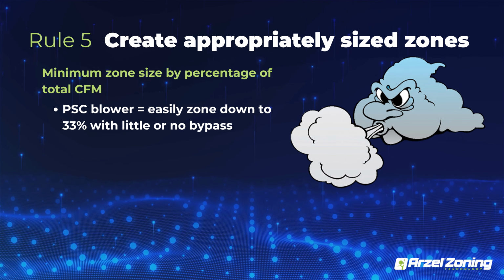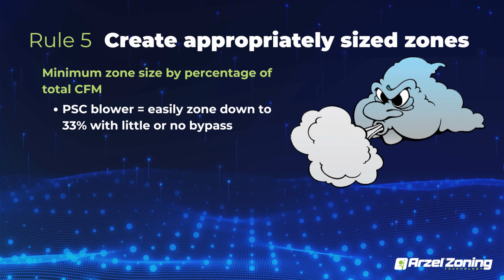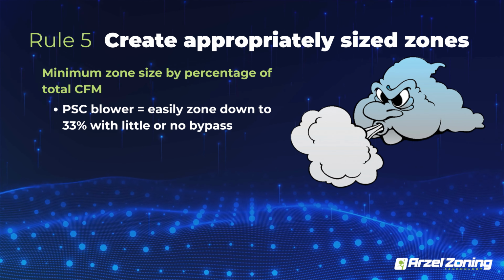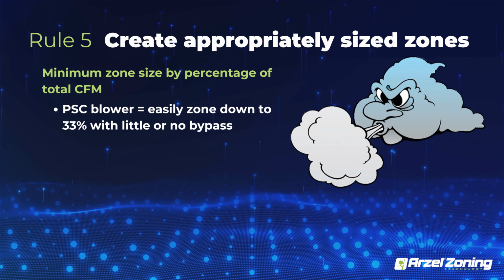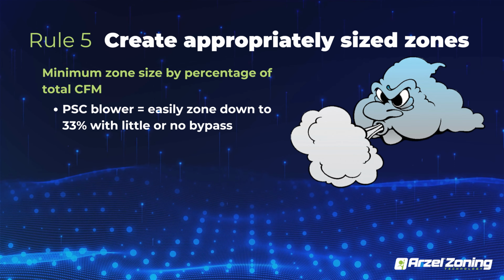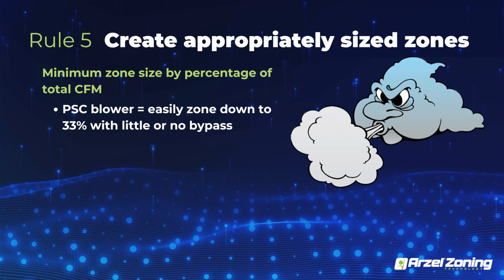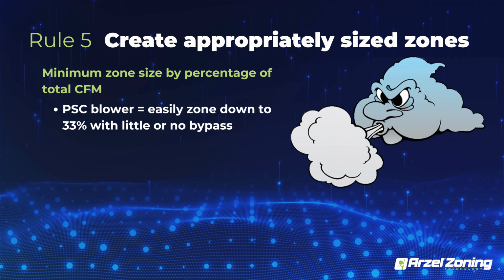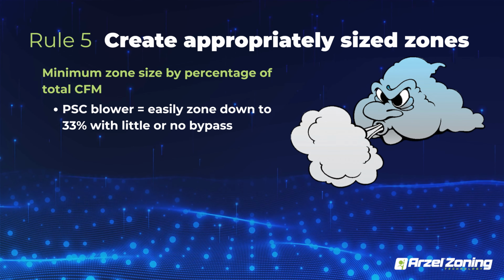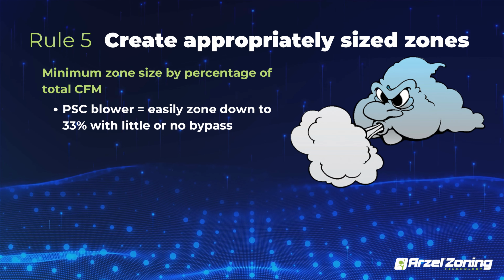For a while, California was trying to ban them on zoning systems. They went full circle and said, okay, you can go ahead and use bypasses on systems. The problem with bypassing is that typically they either get oversized and/or overly adjusted to open too much when the system is running, stealing valuable static pressure, taking a load off the equipment, and other things that we'll talk about in bypass design.